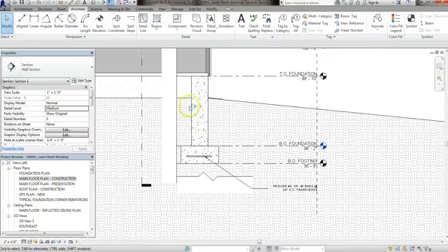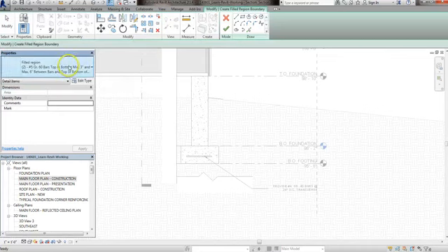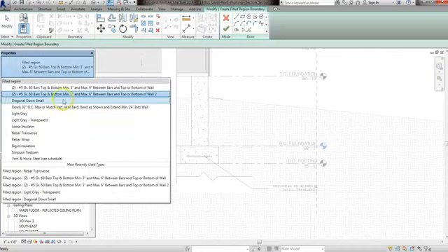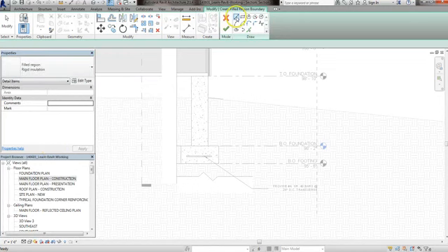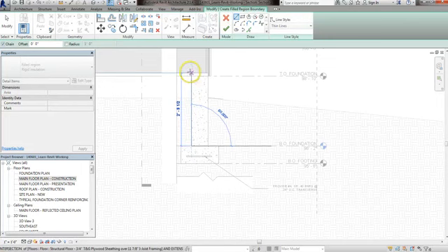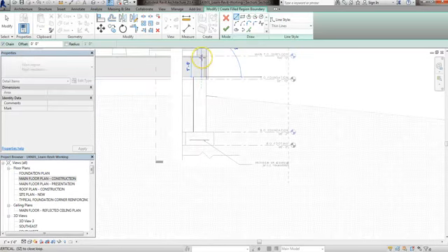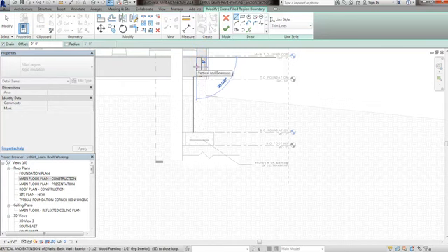The other thing, make sure on this insulation, guys, when you're making that filled region, it should be rigid insulation. You're going to have to make each one at a time. There's 2 of them in there, and you can't make them at the same time. And actually, before you make this, let's just make it 3 inches. There we go. Wait, we can probably look.